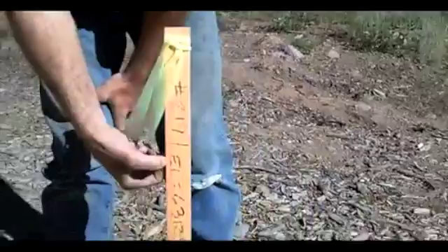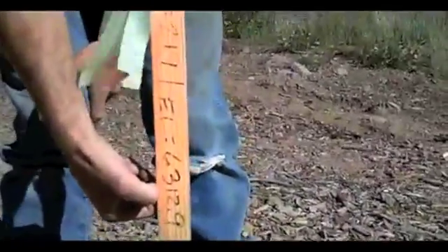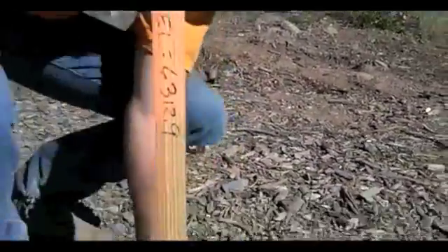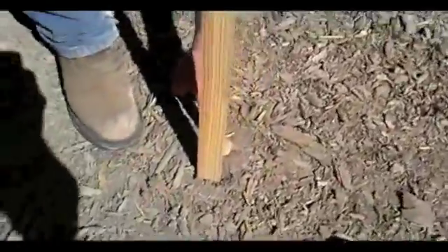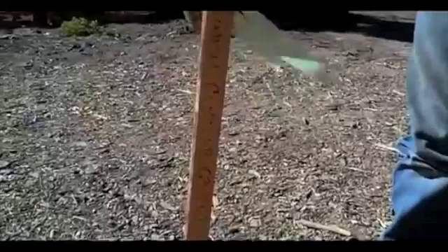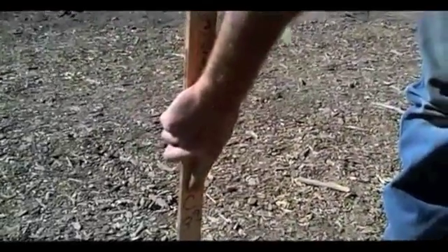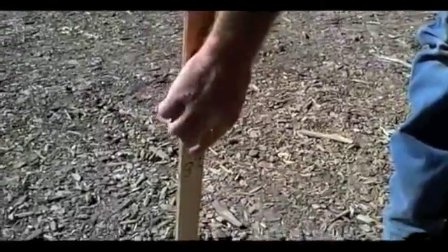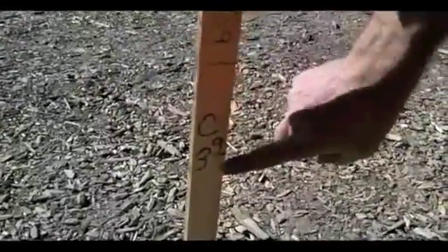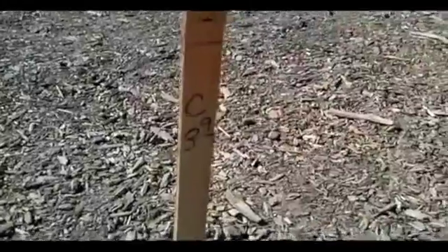This is stake number 219. You can go to your sheet and look for it. It gives an actual elevation, 6312.9, and that'll be to this pin in front of the stake. And on the other side of the stake, it's going to show finished contour, 6309. So we look at the elevation, we see what the finish is going to be, and they give us an actual cut. The C stands for cut, and this is how much your cut's going to be, 3 foot 9/10.